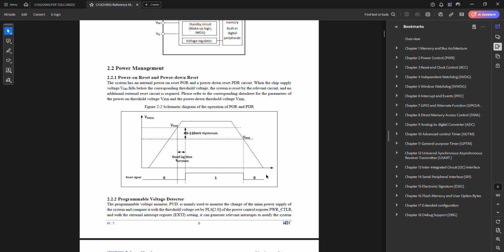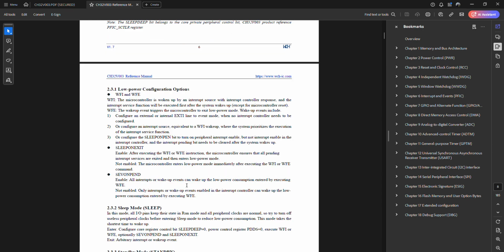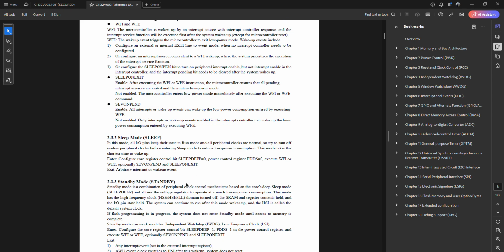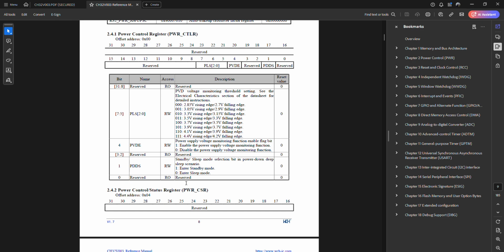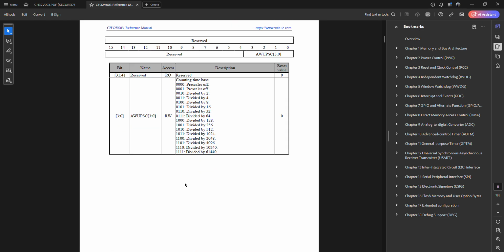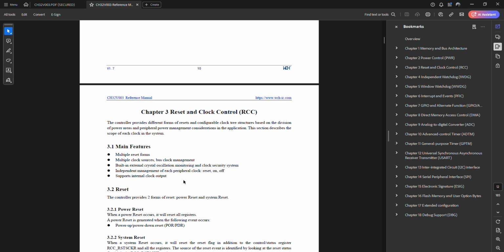But it's very interesting because the CH32V003, unlike the other two microcontrollers I just mentioned, is a 32-bit microcontroller, and it's quite similar to the STM32s, although it's not an ARM microcontroller. But in terms of coding and hardware, the whole thing, I will say it's very similar to the basic STM32s, and it's not that far-fetched that some people will say that it's a copy.